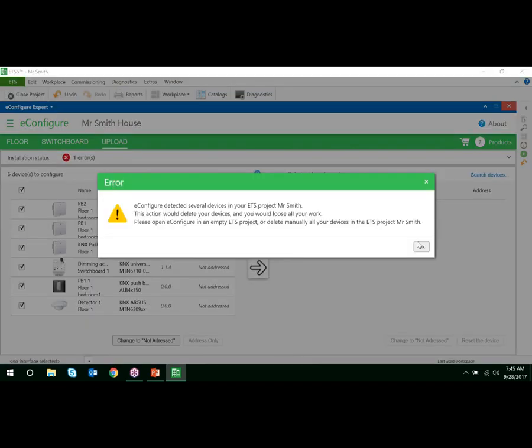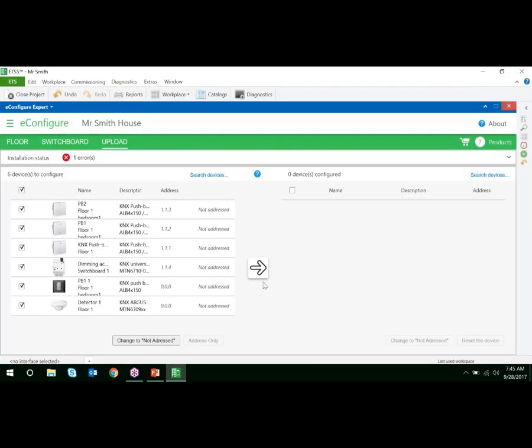Yes, I'm not connected, so it will not work now, but normally you have a pop-up when you are connected to say which gateway interface you want to use. Automatically, it will scan if you have a gateway on the network, and it will propose the one if you have one. If you don't have one, you need to connect, and automatically it will appear and you can use it. So USB, IP router, and in some cases, the controllers, because for example, in our offer, we have Homelink and SpaceLink. You can also use them to configure the installation.